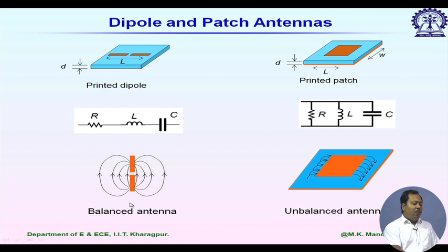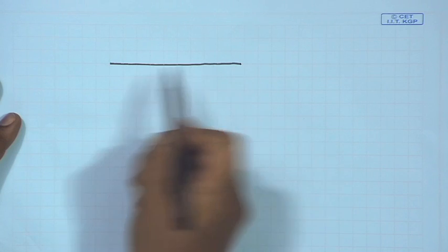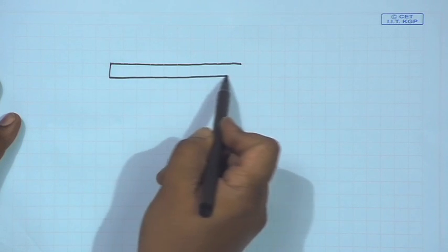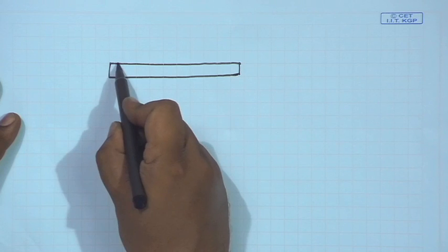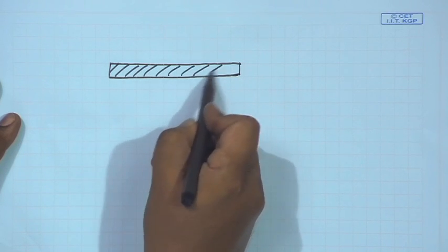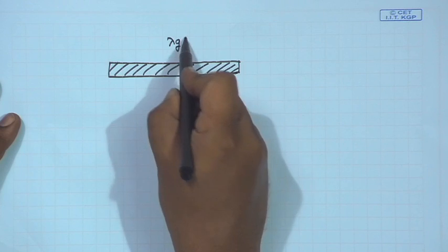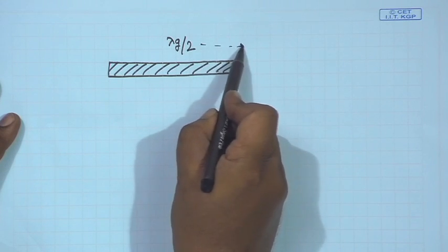We have a radiation null along the wire. And now, look at the electric field plot for a rectangular patch antenna. For a rectangular patch, it radiates from its fringing field. Let me discuss a little more on this fringing field, how it radiates. Let me start from a very basic resonator. Let us say we have a microstrip line resonator of length lambda g by 2, obviously at the resonance frequency.